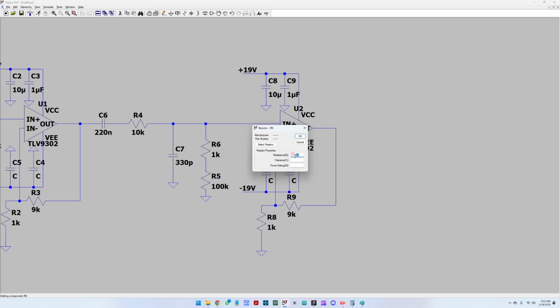This means that we can take maybe a 20 kilo ohm and a 10 kilo ohm resistor here for the feedback. One thing that we have to remove here is the feedback network. So the output from the operational amplifier has to go through the biasing stage, go through the driving stage, and then come back as feedback to the operational amplifier. Okay.